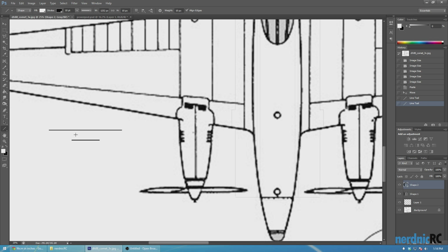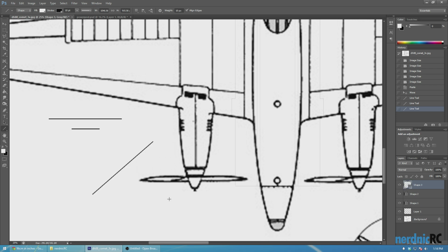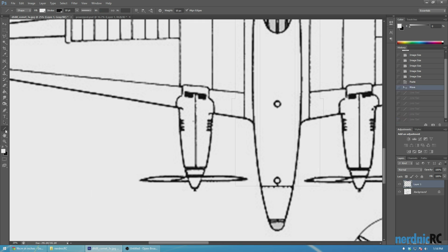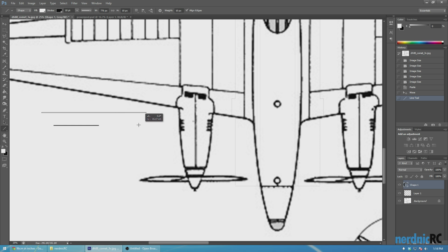One of the things that you'll want to do as we move forward is do something consistent, right? You don't want to draw a line that's at an angle and then try to draw another line that's the same angle. It's very hard to line them up and make them the same. So it's better to start with two 90s and then rotate the whole thing together, which again we'll get into more later, but the line tool is really going to be one of your main tools that you'll use, and knowing the shift, click and drag is really important. So again, I'm just clicking, holding down shift to lock it, continuing to hold shift while holding down my left mouse button and then letting go to save that line.